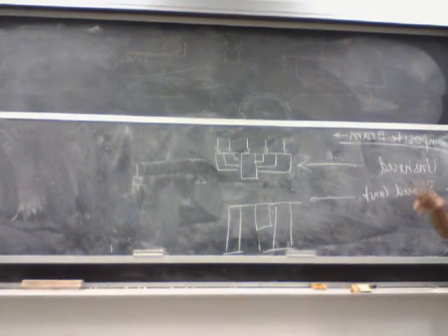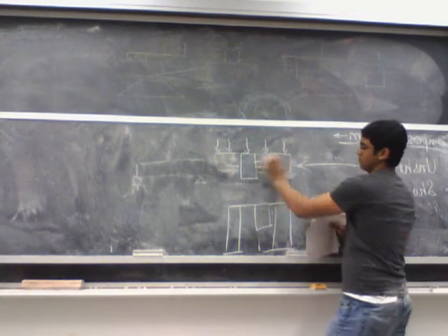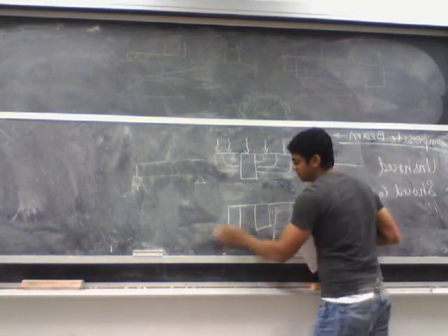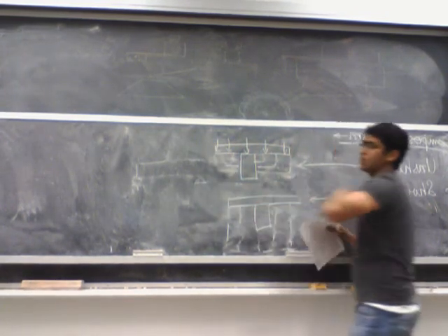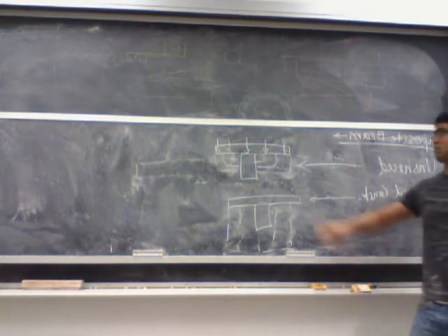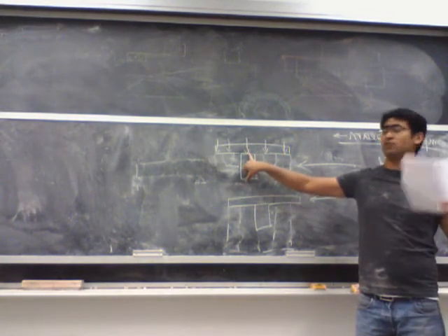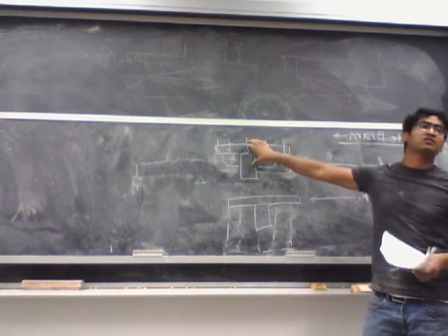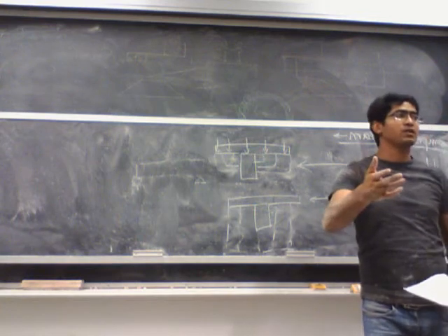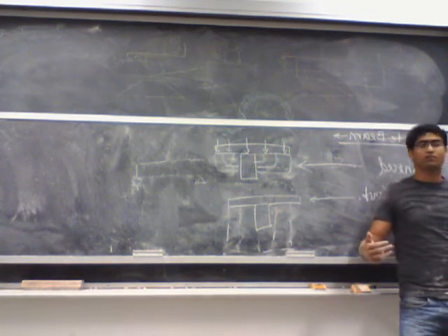Okay. Now after that, once you have poured the concrete, you wait 28 days for the slab to gain enough strength, and then you remove all your shoring, whether it's shored or unshored construction. Now what you have is a composite section with a girder which was cast at a previous time and might have a different f'c or concrete properties, and a slab cast at a later time, which again might have different concrete properties, f'c, Ec and so on.